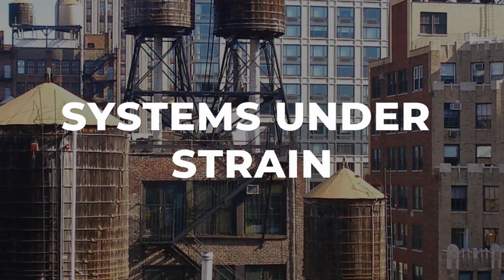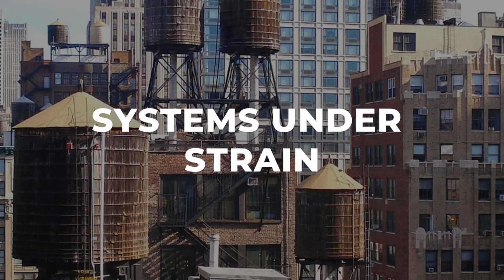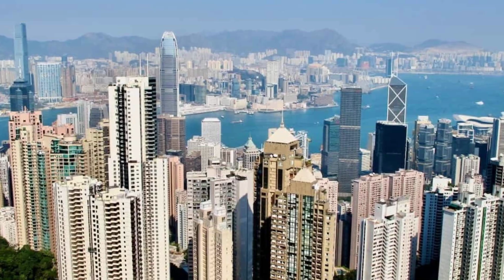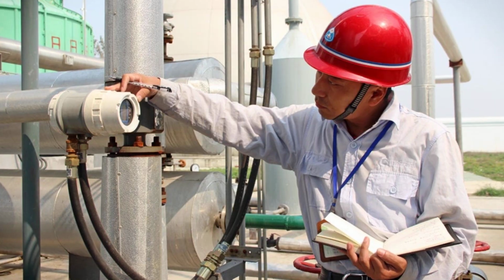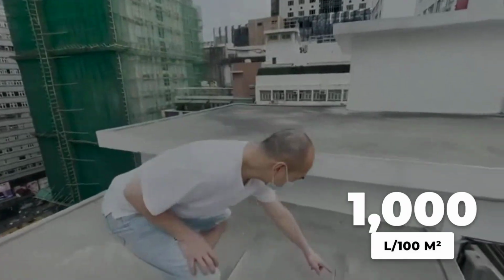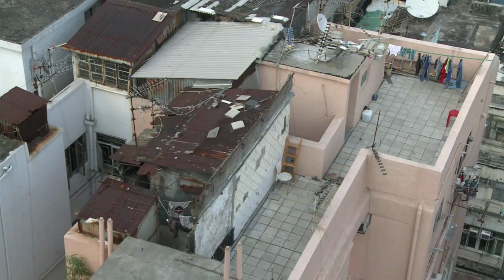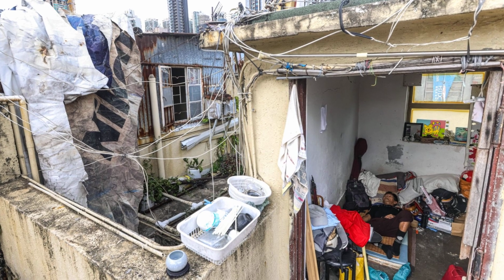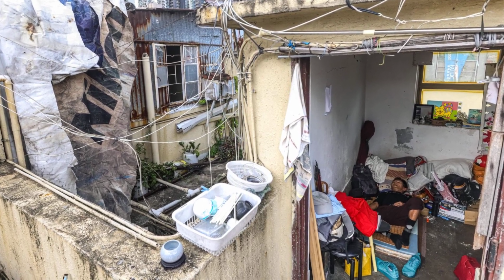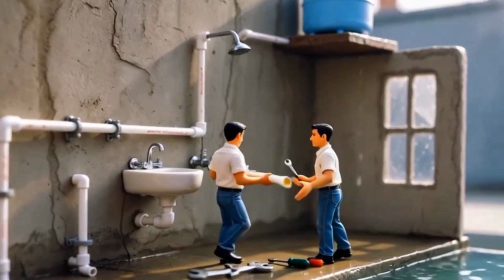Water, power, and drainage in high-rise buildings are engineered for a fixed population. In cities like Hong Kong and Manila, water systems are set to 400 kilopascals, with rooftop tanks capped at 1,000 liters per 100 square meters. When unauthorized rooftop units appear, tank volumes swell and push pressure past safe limits. In Sham Shui Po, 2019, overloaded tanks forced emergency shutoffs, leaving lower floors with unreliable water. This is a strain on water.